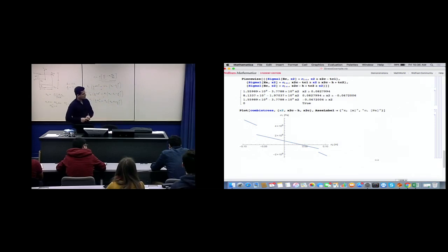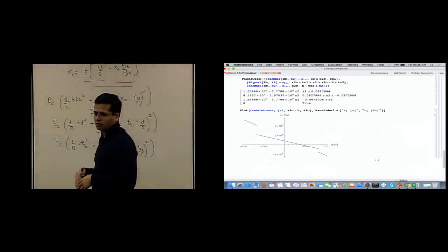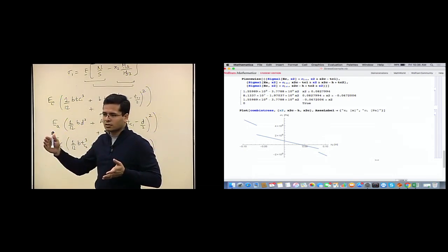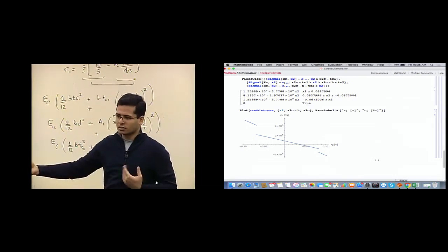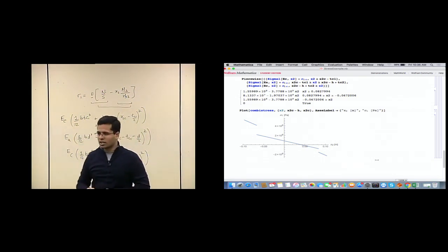And how high the axial force would need to be is governed just by this analytical expression. If this expression is 0 and x2 goes out of the domain of the cross section, it means you have a neutral axis which is outside the cross section. So this expression governs where the neutral axis is.